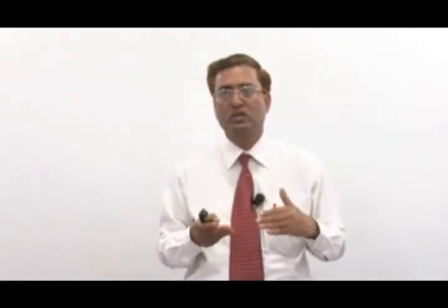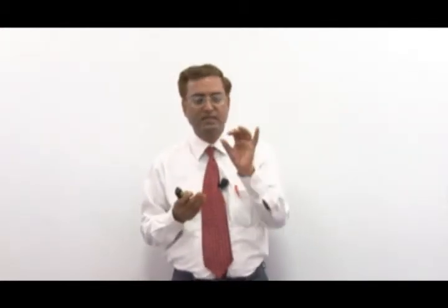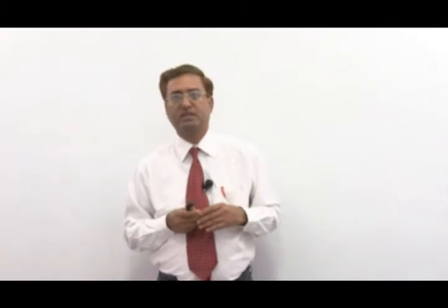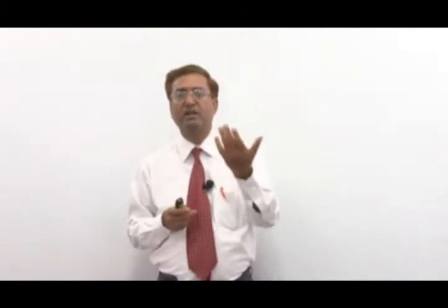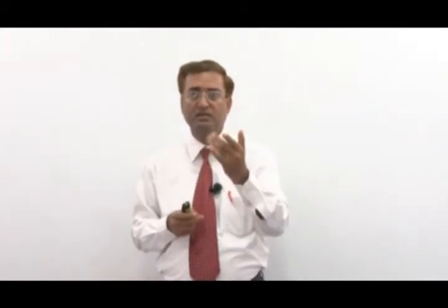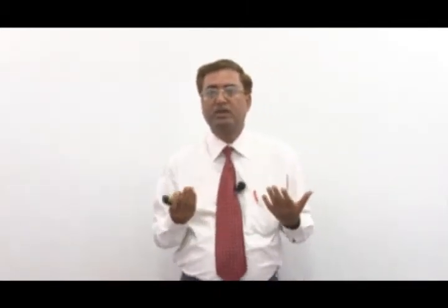So, 2 mu sigma y multiplied by dx, where dx is the element thickness that we are going to take, multiplied by z, then minus sigma x multiplied by h multiplied by z, and this summation has to be 0. If you divide it by z, because z is on all the sides, one can simply get an equation which is d sigma x plus 2 mu sigma y dx divided by h, and that is equal to 0.